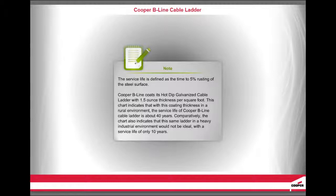Cooper Beeline coats its hot dip galvanized cable ladder with 1.5 ounce thickness per square foot. This chart indicates that with this coating thickness in a rural environment, the service life of Cooper Beeline cable ladder is about 40 years. Comparatively, the chart also indicates that this same ladder in a heavy industrial environment would not be ideal, with a service life of only 10 years.